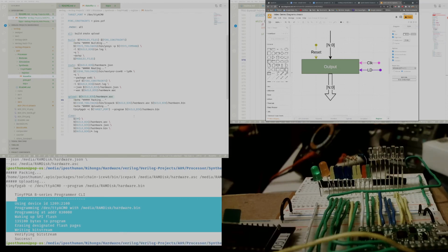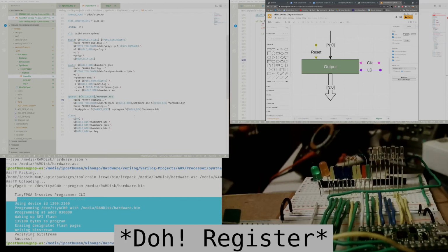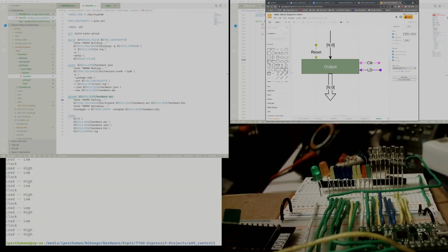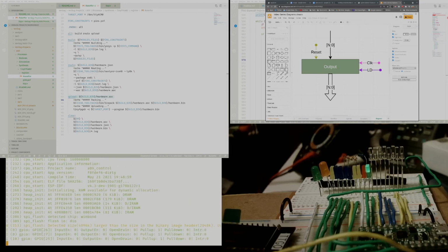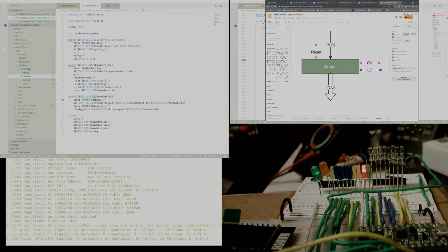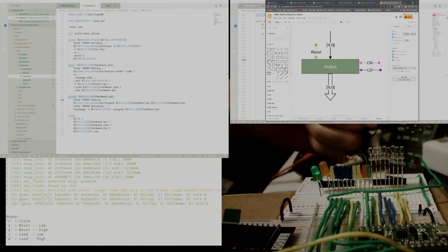So let's start by resetting the register. So we come over here, and now we're going to connect with our ESP32 program via the monitor. So we connect, and there we go. Now if you notice, the lights here have come up in some random configuration, and that's because the initial statement in our Verilog doesn't really honor the initial statements when you're synthesizing. So you basically have to connect and disconnect a couple of times until you get it to come up correctly. See how it's there? Now see, it's come up correct.